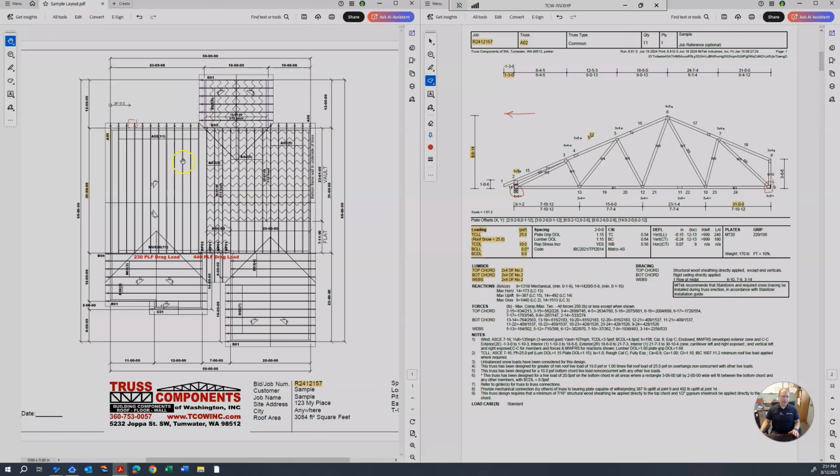So our placement plans, like we've alluded to, they show where each truss goes based on the label of the truss, A1, A02, A03, and so on. And different companies will use different labeling conventions. So what we call an A01 truss, that doesn't mean that every time you see an A01, it's going to be a 31-foot truss with this profile. That just happens to be what we use for this layout. But the layout indicates where each set of trusses goes. And so we're looking over here at the A02 on the right of our screen, and we can see that there are 11 of those on this part of the layout over here.